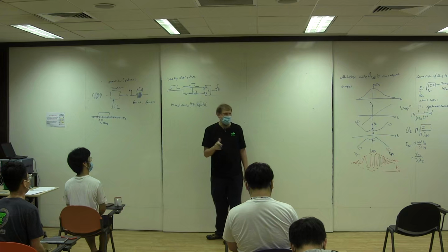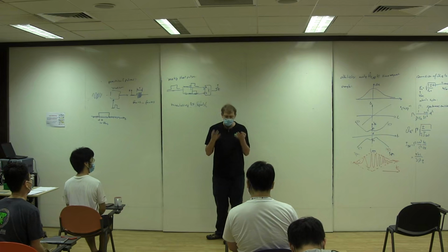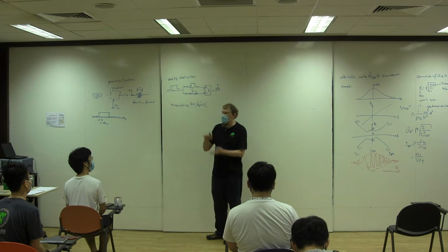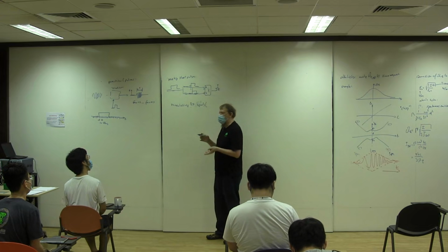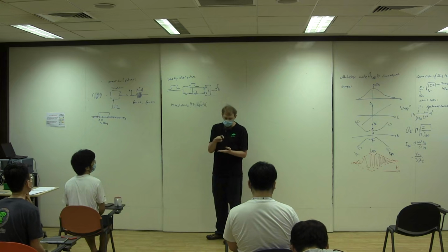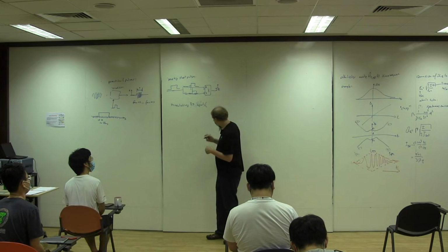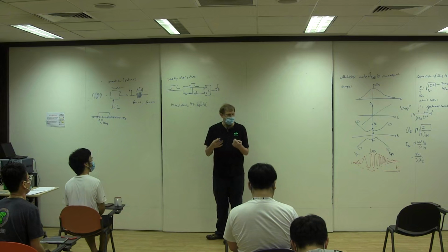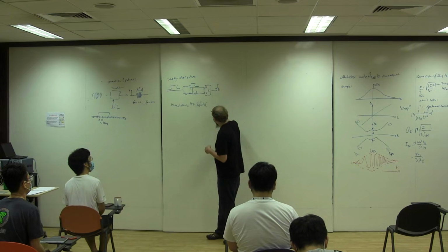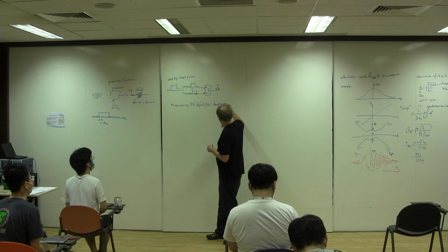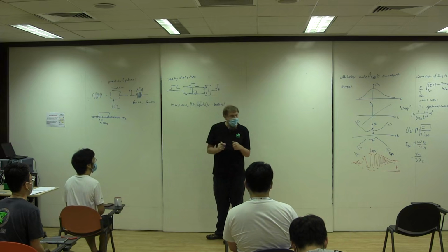And that could be, for example, you want to drive hyperfine transitions in an NMR scenario. There the energy levels are tens to hundreds of megahertz, so the connecting fields that transfer population from one state to the other are on the order of some radio frequency signals. Or for these acousto-optic modulators, you need to create a sound wave that scatters the light off. This is 10 to maybe 1,000 megahertz as a typical range. How do you go about that practically?